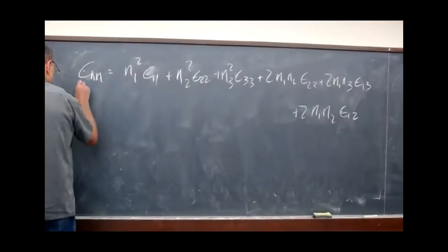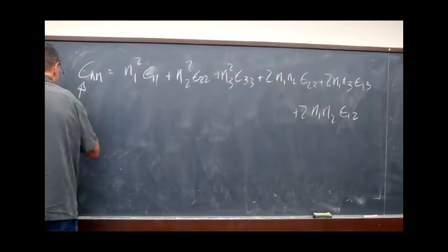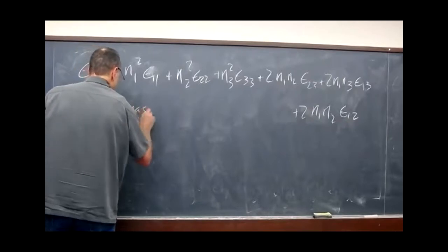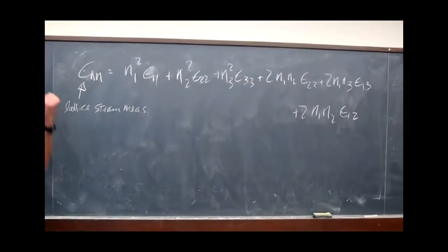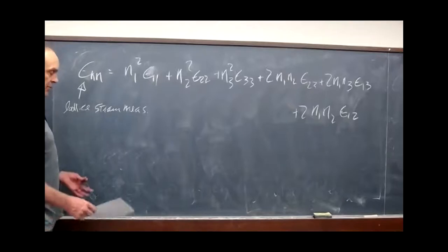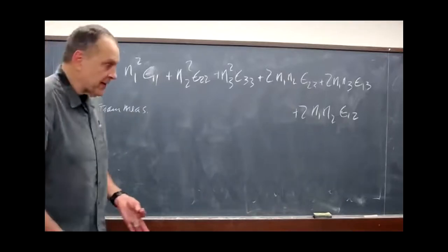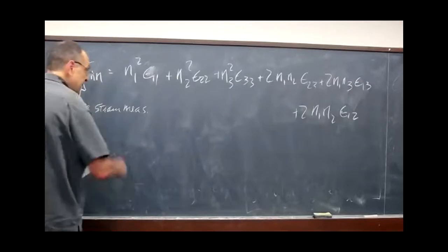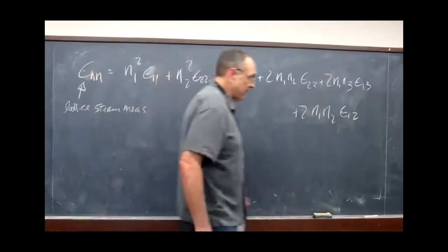So this is from one lattice strain measurement. I keep writing that because we'll track this all the way back. This is our delta D. This is our delta G. This we get from the expression, because we can always compute the G vectors, and so we can always look at that quantity. We can measure that. We can extract that from our experimental data. So now we can write this in a matrix form. I'll let you write this down first.